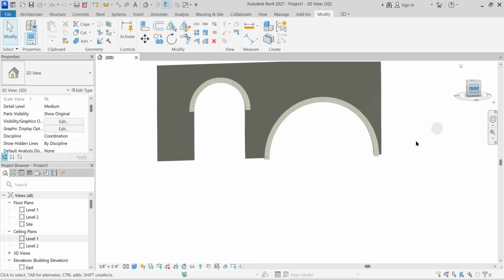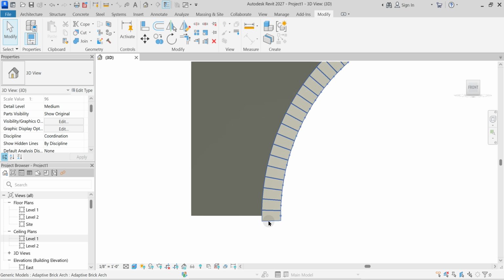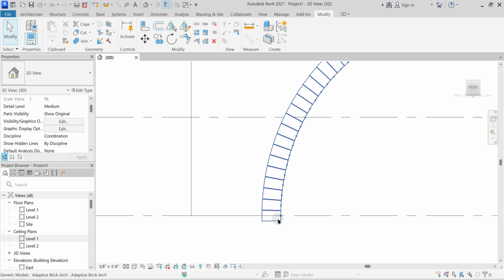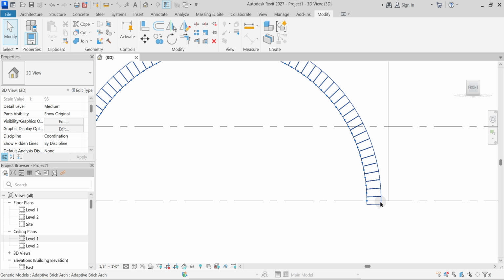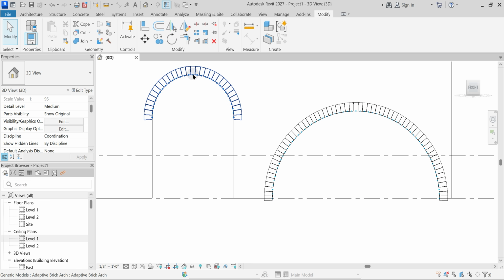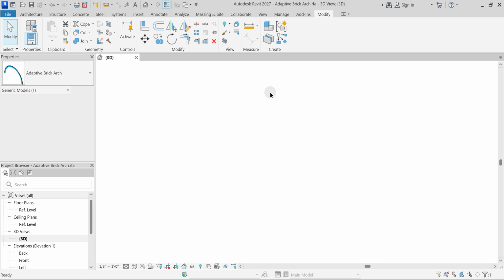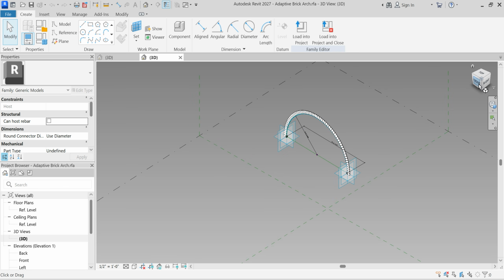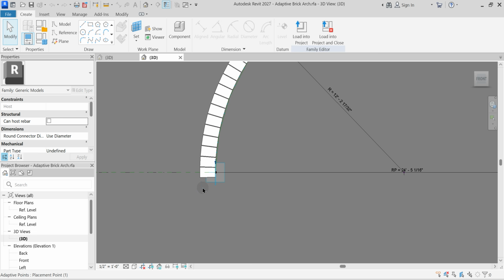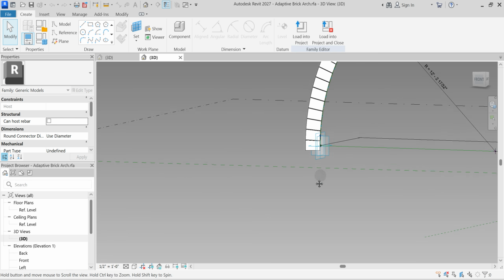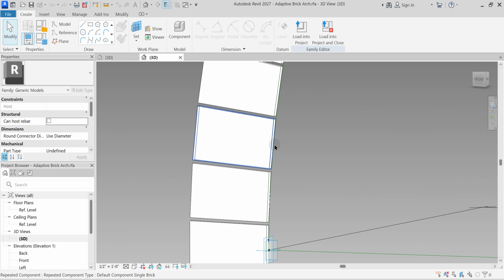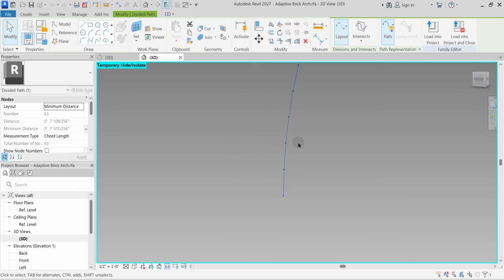Now, if I just go to the front elevation, you will see this extra over here, and over here, both. So how to get rid of that? So select this and go to edit family of this and come to front elevation, and actually not front elevation. Press tab until you find this dot H5. Okay. So this beginning indent and end indent. These are the instance parameters.